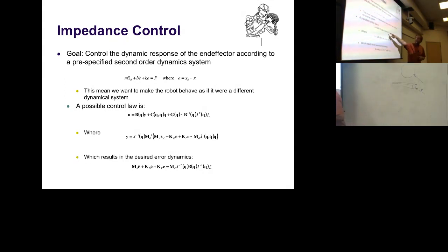Again, for your physical system, we're always relying right now on models. One of these things, whenever this B inverse pops up, hell may break loose. The inertia matrix is lovely. It's the rigid body inertia matrix. But inverting it may be a pain. It may have bad conditioning because some degrees of freedom are very low mass, some others are heavy mass. And if you have modeling errors in there and you take an inverse of a badly modeled inertia system, it becomes even worse.